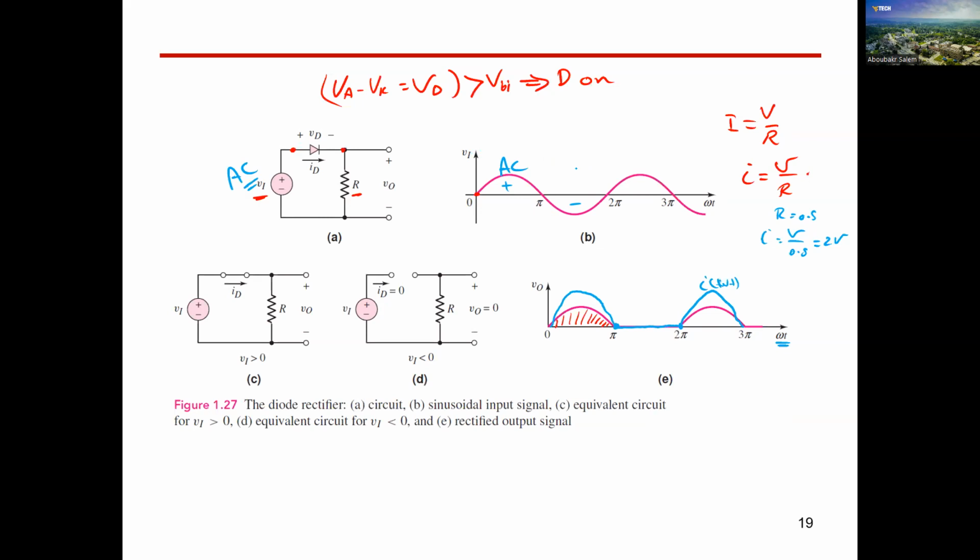For that, guys, we discuss in other courses what's called the Fourier series. So with Fourier series, for any waveform, you will have an AC component and a DC component. DC component means the DC part of the waveform. AC component means the AC parts in a waveform. And I said AC parts because we have different frequency values. So it could be the fundamental frequency, it could be second order, it could be third order, and so on. So this is what's called the Fourier series. I think you will learn that in signals and systems in another class.